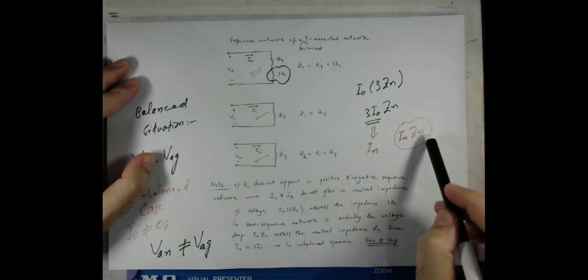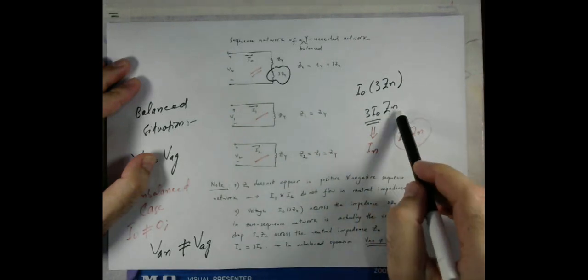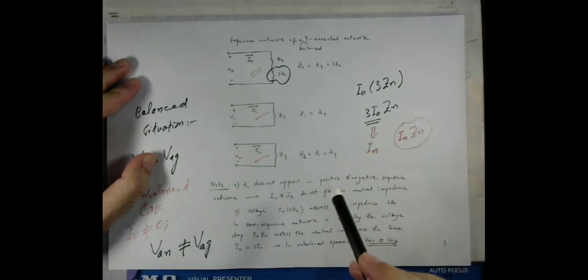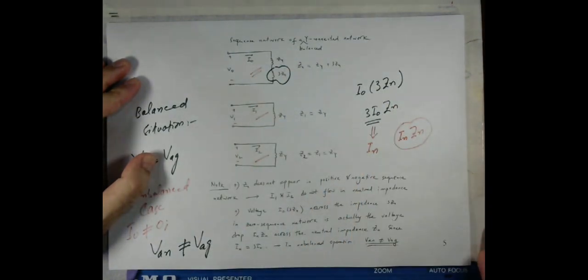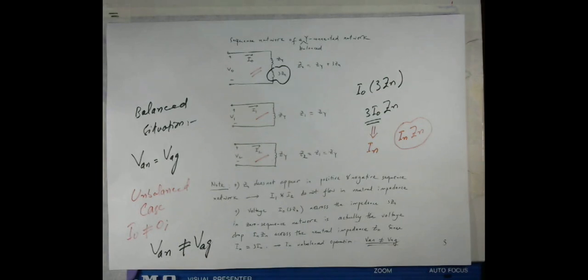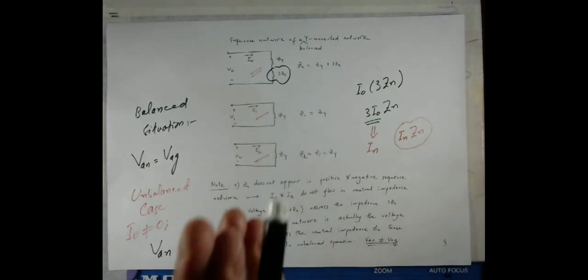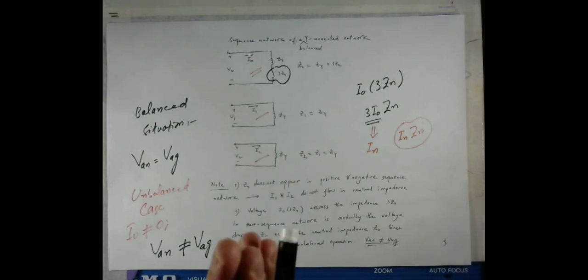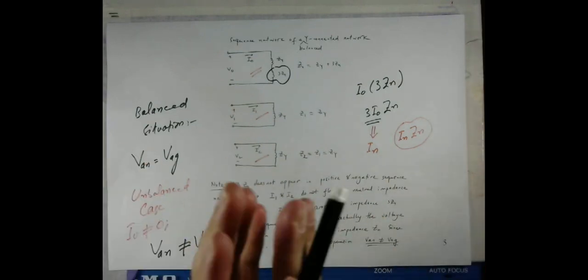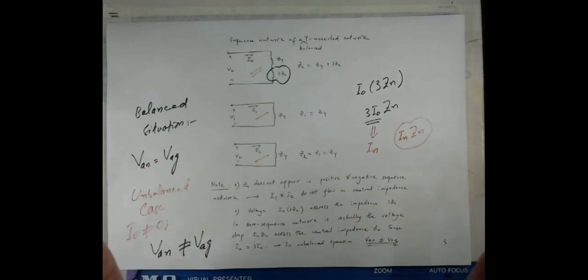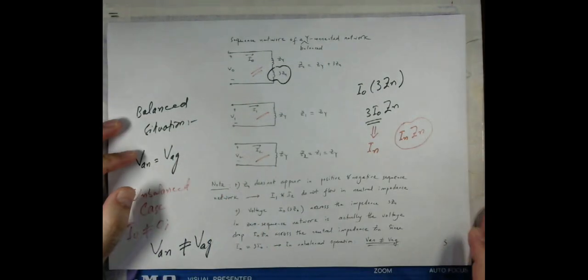So to the neutral current it is the impedance Zn which is offered, but to the zero sequence network 3Zn is offered. So we made these observations, and the conclusive point was that the zero sequence current only flows through the impedance to the ground. The other 2 sequence currents do not flow through the Zn impedance.